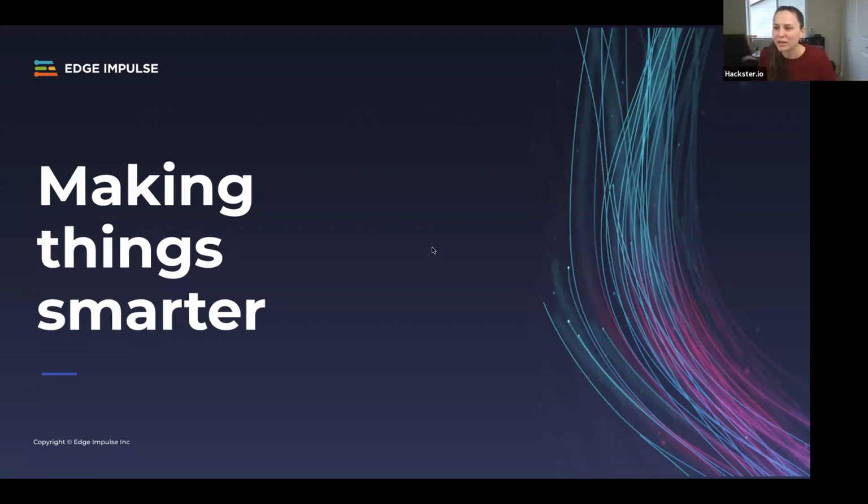Awesome. So what is the hardware to acquire sound on the LaunchPad? Yeah, so the hardware on here, I don't have the exact model name of the microphone, but it's a small I2S mic that's included with the audio booster pack that we actually advertise. If you go to the documentation on our website, we show, okay, you need this booster pack, you plug it in the LaunchPad, and then that collects audio at a 16 kilohertz frequency, and it's running inference off of that.